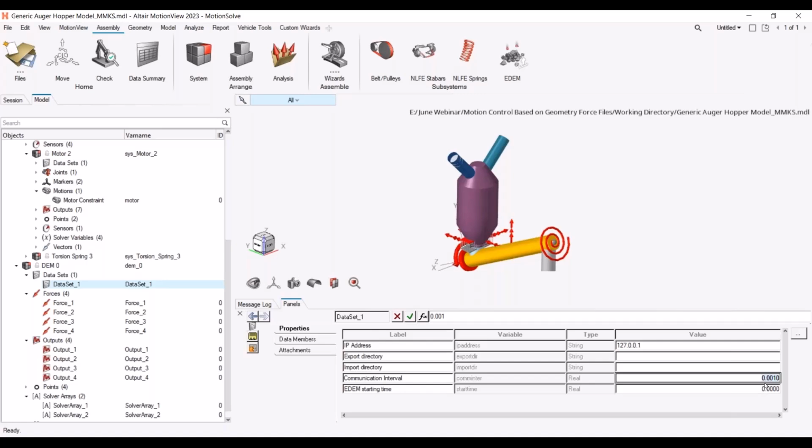So a 1-to-1 communication interval, perhaps up to 100-to-1. So if your time step is a kilohertz, you could get away with 100 hertz or even 0.1 for the communication interval, depending on the dynamics, depending on the specifics of your model. Trying to think of what other nuances or approaches you might want to vary.